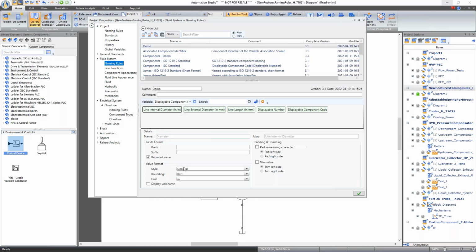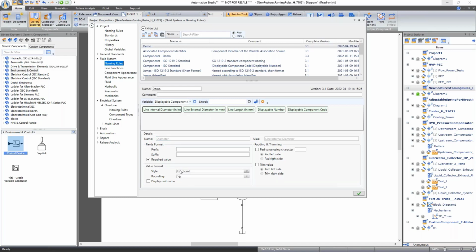If you're using inches, you can also change. So I can change here to fractions. Now, once I select fractions, I don't have the option for units. So we're just assuming automatically that you're going to be in inches. And then I can change the precision. So here I can set 1/16 of an inch.